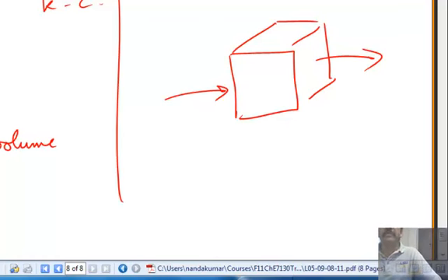But it is best to study fluid mechanics in the Eulerian reference frame. Why? Because we cannot tag every fluid particle and follow where it goes. We can go in many different directions. So we observe at a particular place how much liquid is coming, how much liquid is going, and from that we study the velocity, momentum, etc. So the Eulerian frame is the best description for fluid mechanics. Lagrangian description is probably the best one for rigid body dynamics. But there is a relationship between the two, and one should be able to go from one to the other.